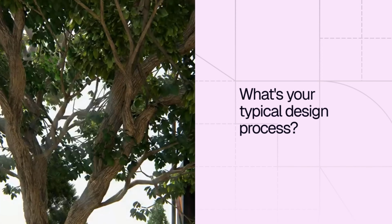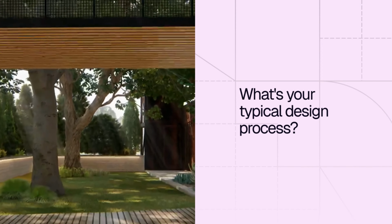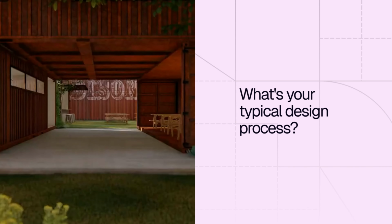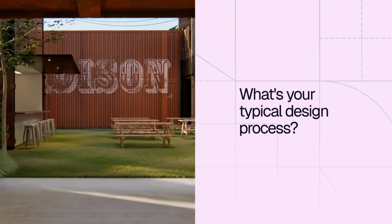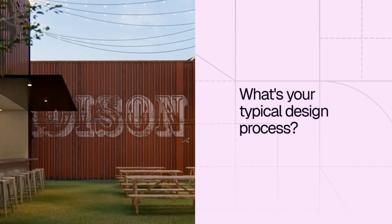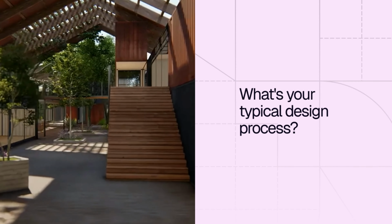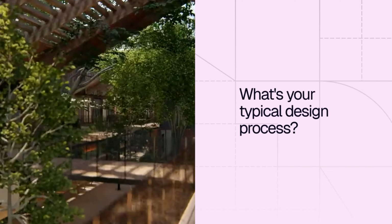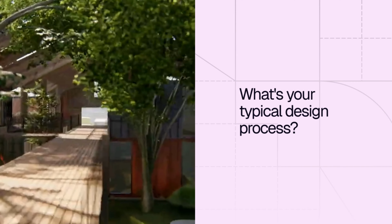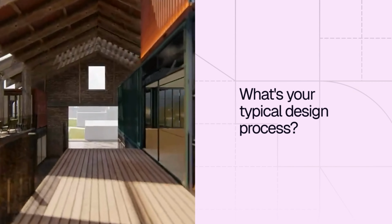The technical design process is getting the base files. We need a site survey, or some kind of civil site plan, or the base file in CAD. Then I start doing massing models, I start bringing in my families, I start designing and get a good concept going. Once we get past schematic or past design development, we will do some pricing estimation with contractors and make sure we're on budget with our design. And once we get past that, we'll move on to construction documents.